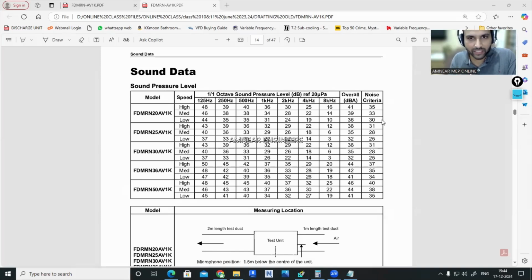That might not always be correct, because when the software or we manually calculate as per the room sensible load only, or even with latent load also, the calculation might be different. So with respect to the room load only, we will be calculating the airflow rate. That has to be satisfied when we are proposing the machine. If you are not finding the perfect match, we have to go for a different model. Accordingly, we have to calculate, select and propose it.